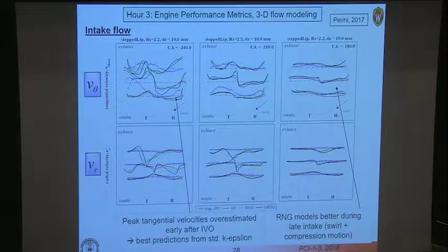They pick up that swirling flow. The magnitudes are perhaps debatable, but at least you're getting those magnitudes. You're even getting the zero point, which is the center of the swirl, which is pretty important, but the swirl precesses around in the combustion chamber. And this, by the way, is all at one height, 10 millimeters below the head. We have comparisons also at different locations, but this is just a sample of that data.